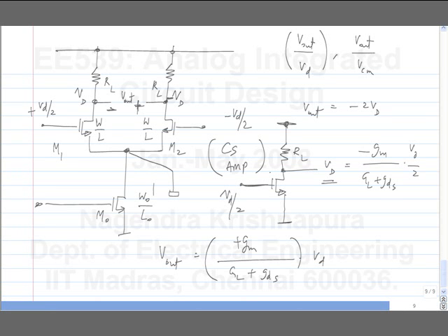So we took a long time to get here, but now all of the differential circuits we analyze will be of this sort. It will be some differential version of common source, common gate or common drain amplifier. So we already have done the analysis ad nauseum for the single-ended circuits. We can go through the differential circuits more easily. So it also gives you an insight that it should be the same as common source amplifier. Right?